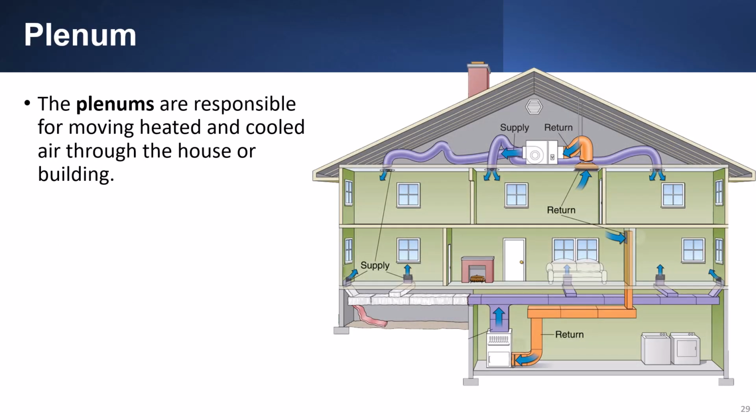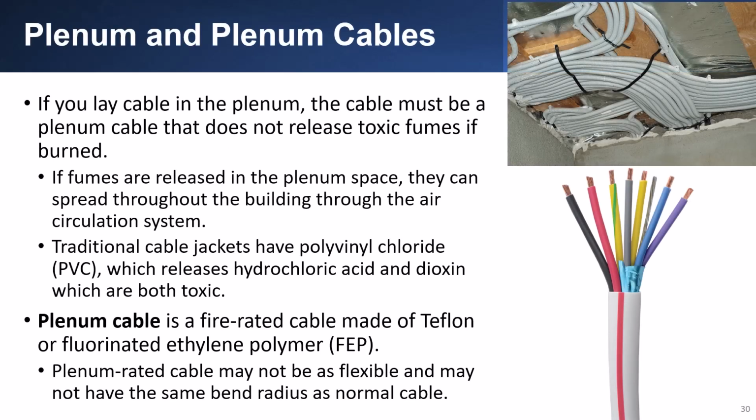The plenums are responsible for moving heated and cold air through the house or building. If you lay cable in the plenum, the cable must be plenum cable that does not release toxic fumes if burned. If fumes are released into plenum space, they can spread throughout the building through the air circulation system.